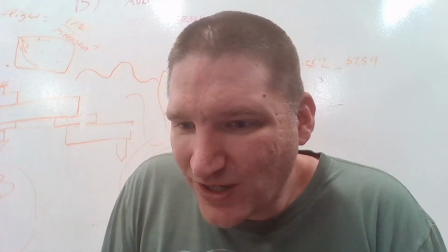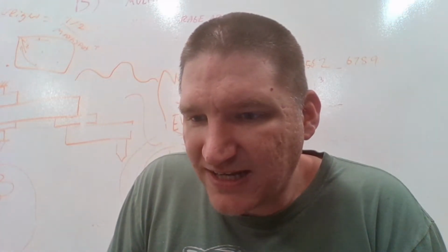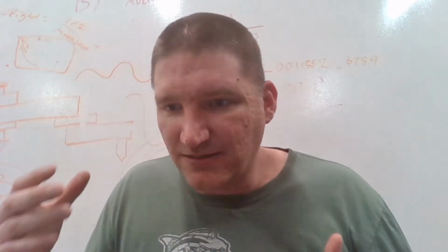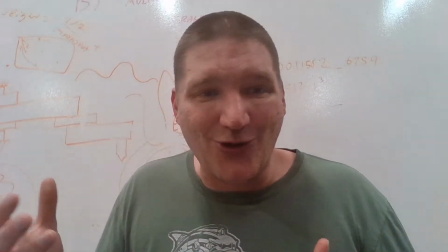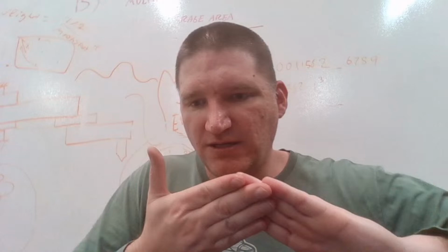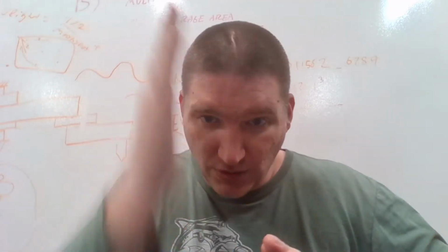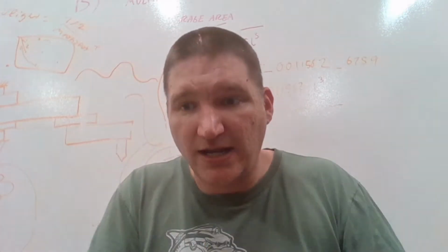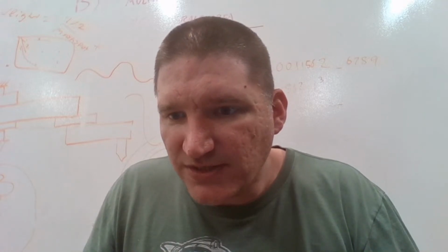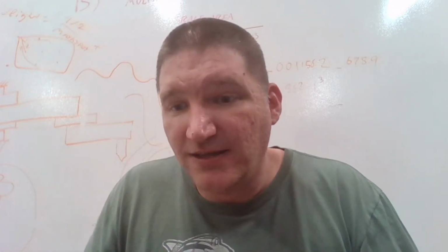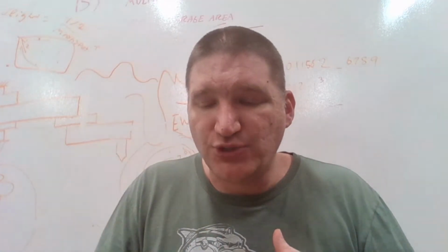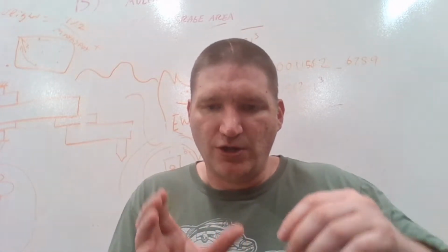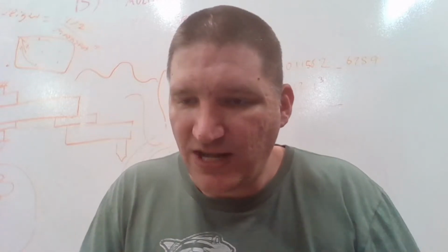And if this has been asked, would the arms be better as a fork design instead of a cantilevered? Okay. Yeah, nobody asked about this yet, so that's a great question. So I don't have the arm anymore, but the arm is what's called a single shear connection, where you can cut with one plane, and the arm will cleave off, and you'll have 2 arms. So like one shear line. The way I'm doing it is called single shear, and you can do better by doing a double shear, where you actually connect. It's like you have one arm go around the other one, and that would have better performance.